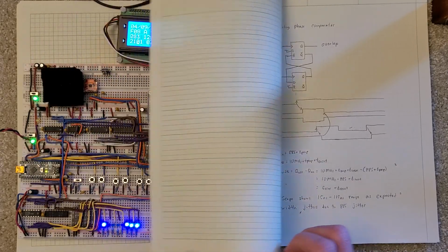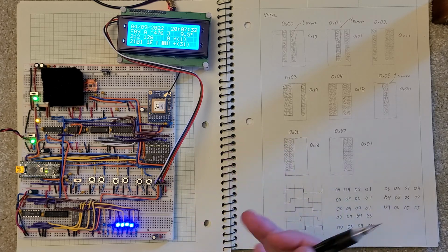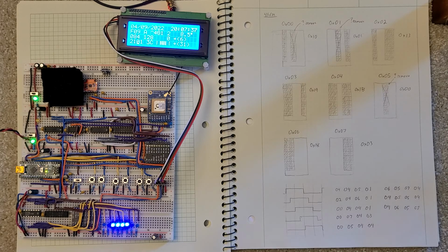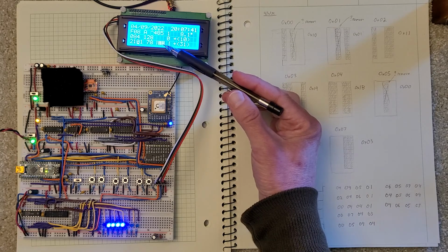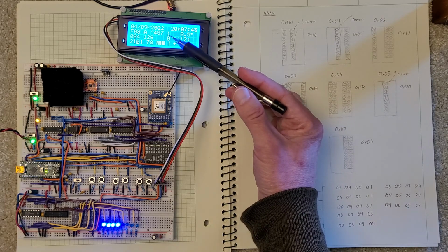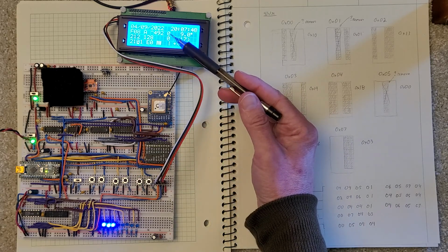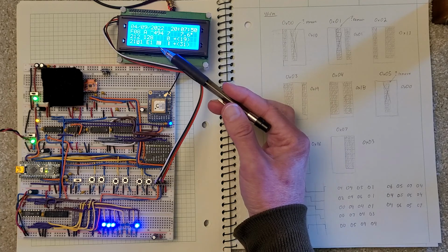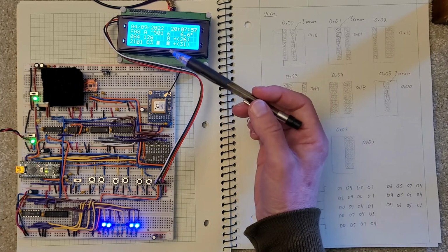But there's a lot of jitter in the PPS clock, and there's noise in the system. And I'll probably do the circuit just for fun, but it's a distraction, because right now, even though this edge is jittering back and forth, the granularity I'm looking at it with this circuit doesn't show that jitter, and very rarely do you see an edge show up and disappear. It's always the steady march.